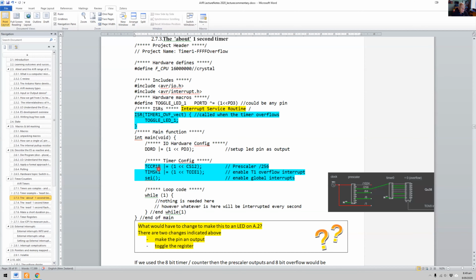So there it is. That's the first bit of setting it. What that does is give us a prescale of 256. Now, you'll notice that I have not cleared bits clock source, timer 1, bit 1, and bit 0. The other 2 bits I've left and I haven't bothered to look at. And there's a reason for that.